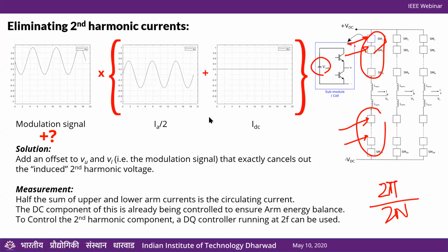However, it is used in applications where it is not possible to have a single device anyway. So let's say your grid voltage is something like 35 kV, right? After accounting for things like headroom and all, this voltage is 60 or more kilovolts. There is no device that will have a 60 kilovolt blocking rating. And so somehow or the other, you have to have devices in series, right? They will obviously have conduction losses, but there's no alternative. You cannot have one 60 kV device anyway.